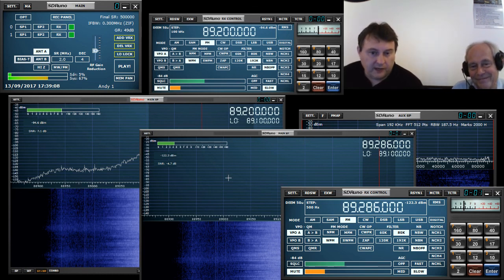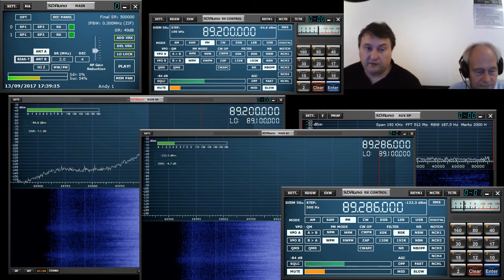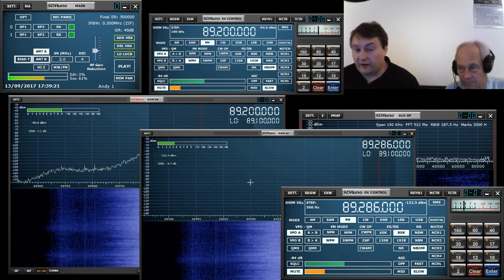Yeah, within SDR, with the RSP you only ever set the LO in the RSP and the amount of bandwidth that you're receiving. The VFO, the signal that you're actually interested in, is a virtual frequency oscillator that is specified within that bandwidth.